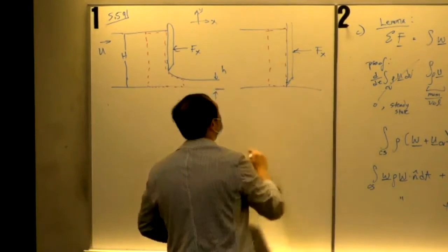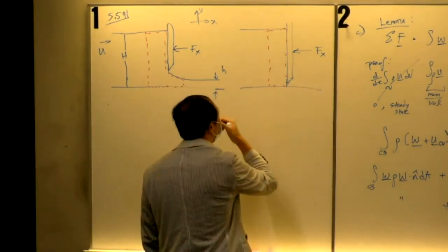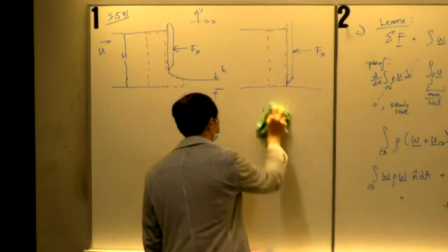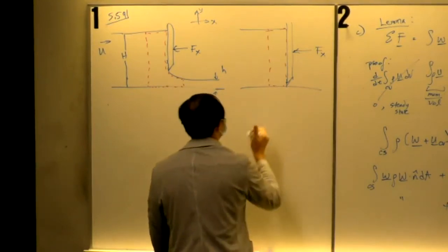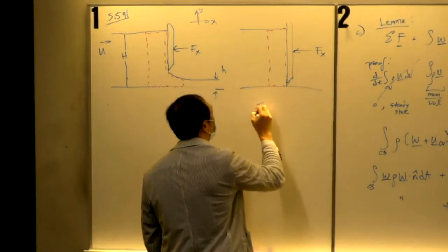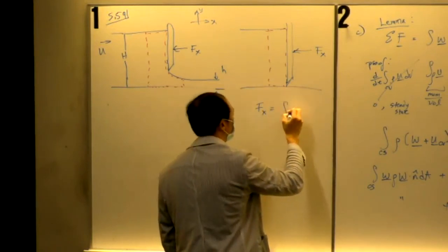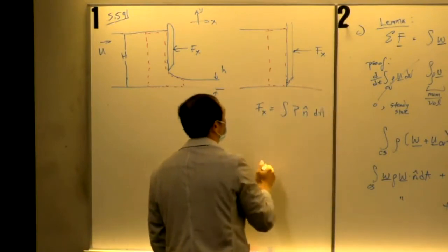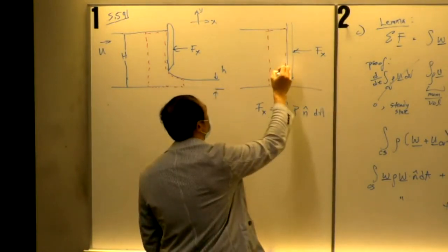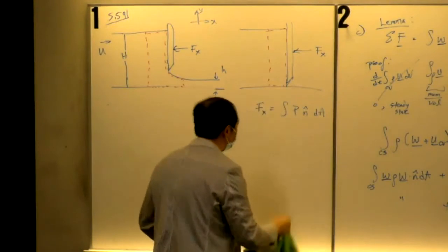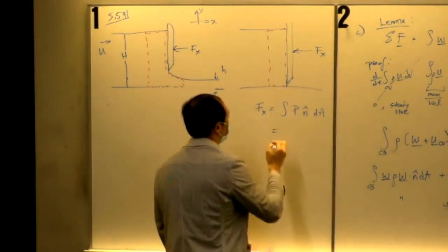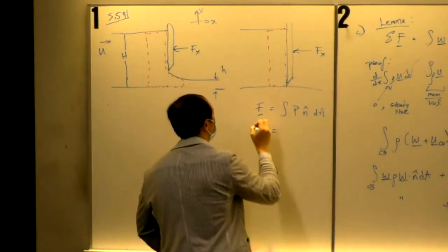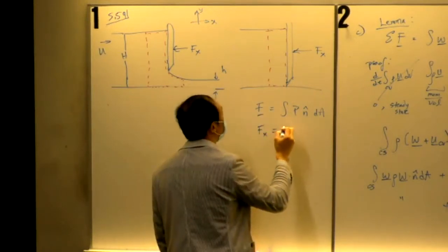So this one gives a blast back to hydrostatics. Rho g. Fx is equal to hydrostatic pressure, so the integral of P n hat dA. Here the n hat vectors are all going to be in the x hat direction, so we'll just call this F in general.